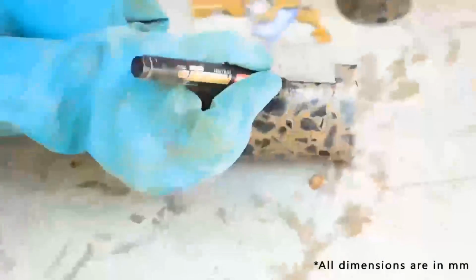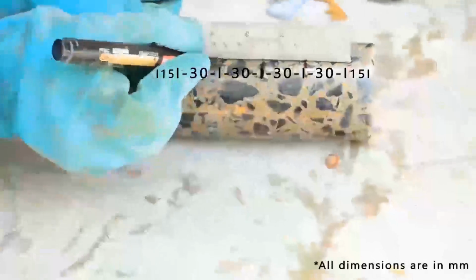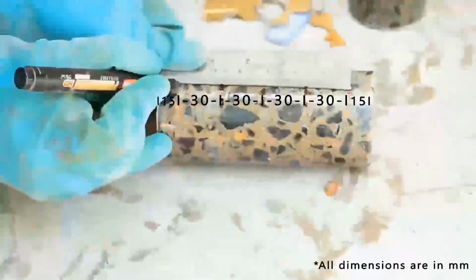After the epoxy is cured well, mark 15 mm from one end, then mark the subsequent points with about 30 plus or minus 2 mm as shown on the screen. This way, 4 specimens can be obtained from one core. Then cut the cylinder to prepare the concrete disc specimens. A concrete cutting machine with a diamond cutting blade is used.